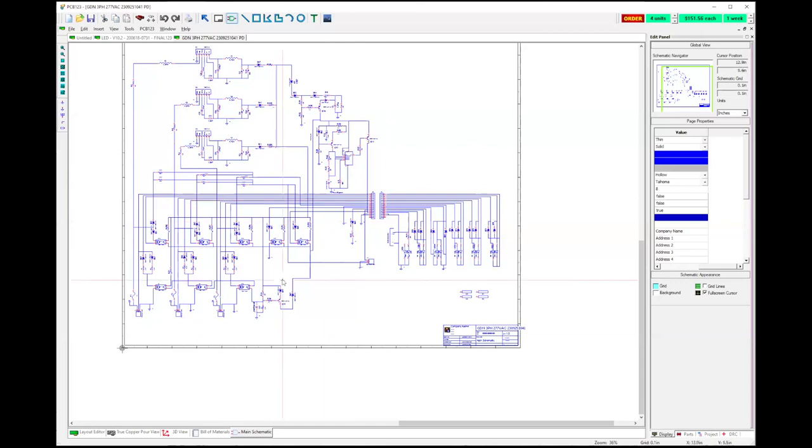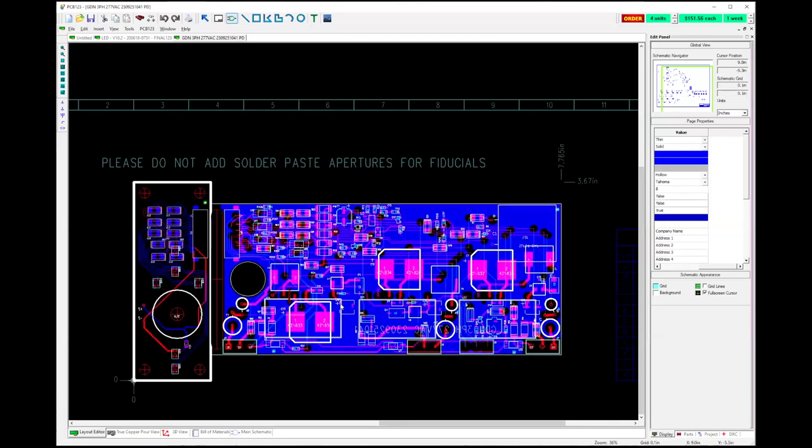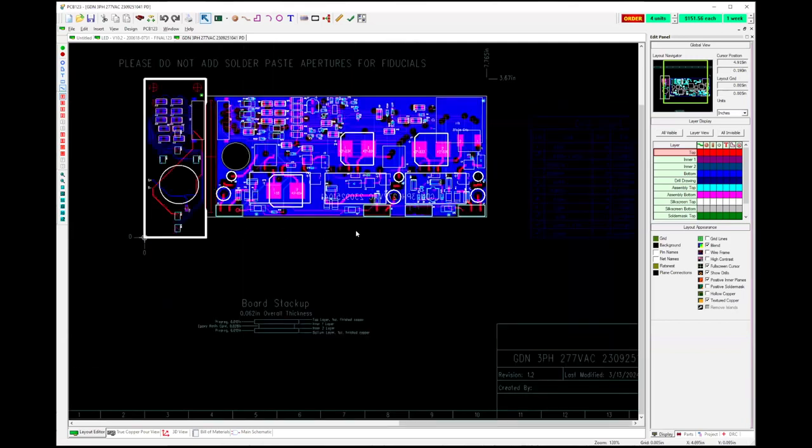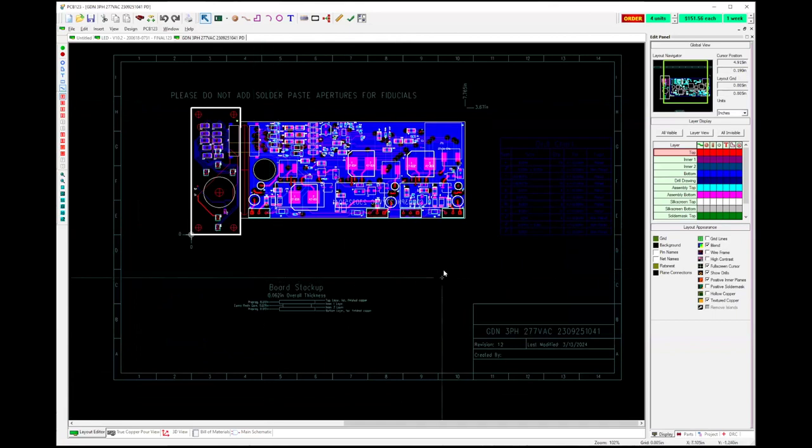After you get your schematic done, of course, you'll go back to your layout editor, and once the schematic's complete, all your parts will land piled up into a stack on the origin. You'll need to move them around and place them on the board logically and per the schematic. And the way I do that is I just take all the parts from this location and spread them out off the board. I zoom out a little bit and I spread them out, like in this area, so that I can see all the parts that I've got.